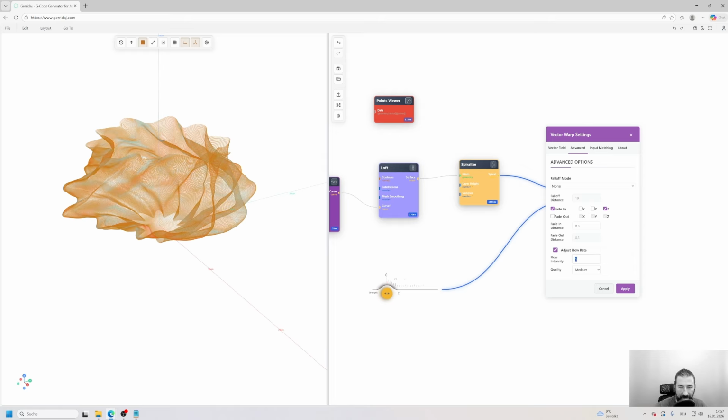And if you try that now, you see it also visualizes: in areas with this blue color, it will generate less extrusion, and in areas with red color, more. You can adjust here the intensity of the flow compensation. It's just by testing out manually, because it's different from printer to printer, from nozzle to nozzle. At least for now, it is not exactly mathematically precise, so you need to experiment a little to find the right values. You can just increase the intensity of compensation here, and it will extrude even less in the areas where the lines are close together, and even more where they are further apart.